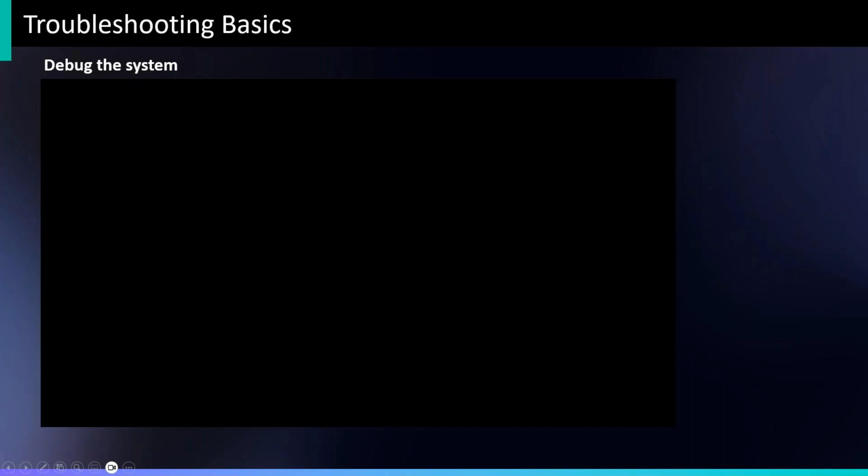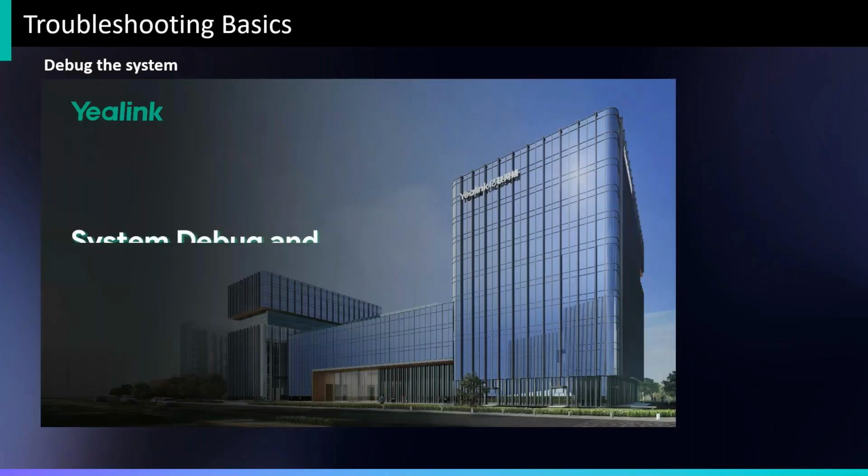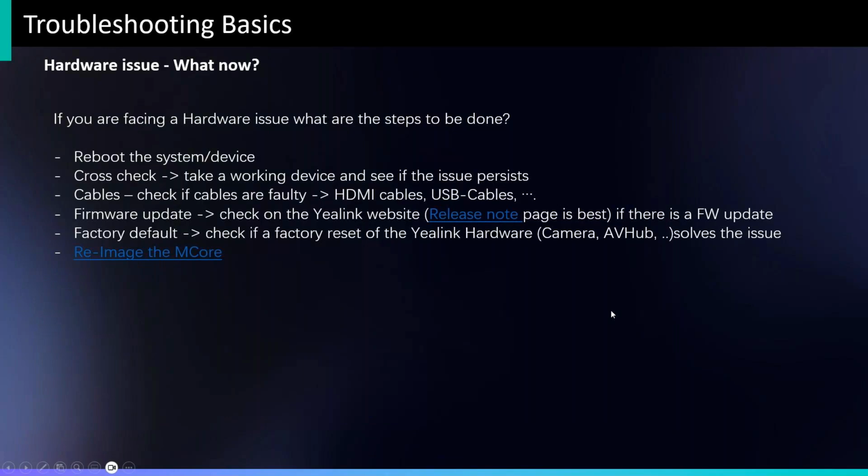Okay, so that's just to show more or less what you can do in live environment testing to see if the linkage is done properly. If, for example, the audio of a microphone is not coming into the meeting to the remote participants, it doesn't mean that the microphone is faulty, because if there is an error in the linking, if you linked something wrongly in the backend, then it actually might be that this is the issue.